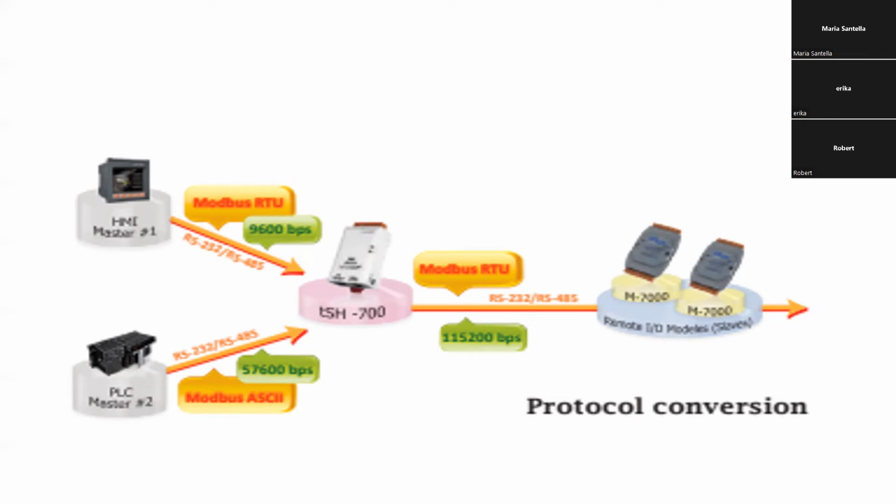Traditionally, Modbus RTU only allows one master device because it operates on a master-slave configuration where the master sends a request, and the slave device that's being spoken to responds to the master. When a second master were to communicate using the same bus, it would cause communication errors. So therefore, it's not allowed. Also, RS-485 is traditionally used for Modbus communication, which is half duplex, so you can only send or receive at one time. Let me show you the next slide.